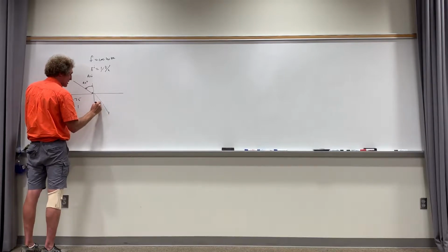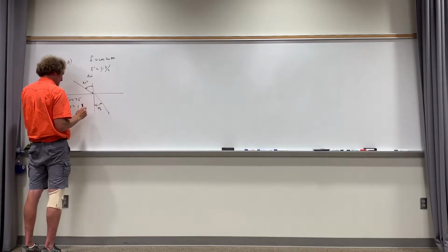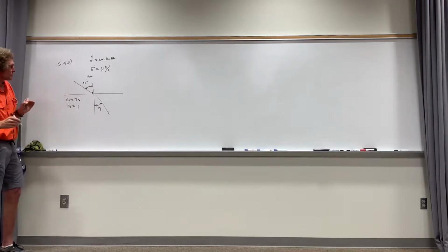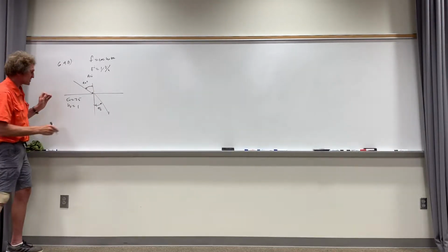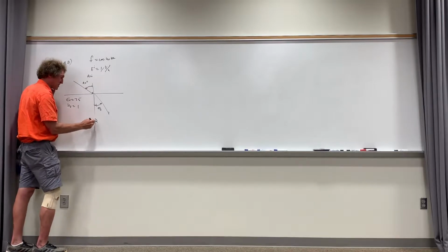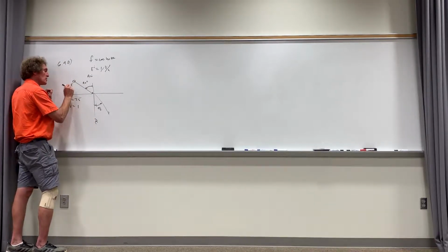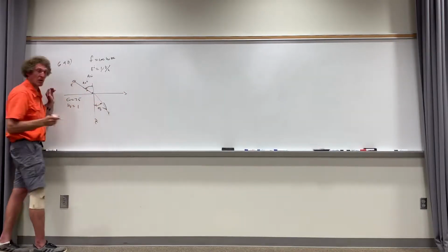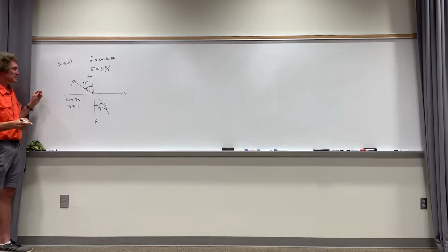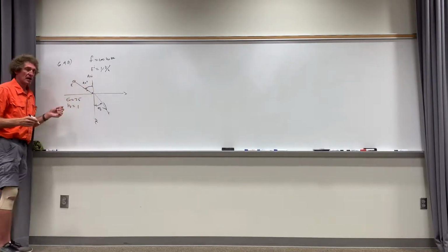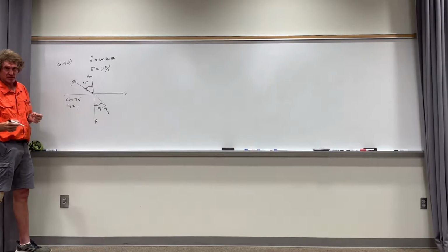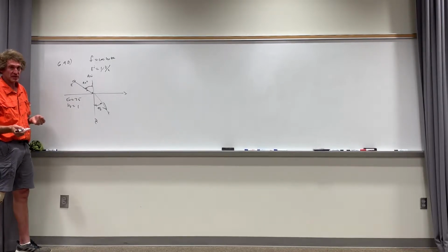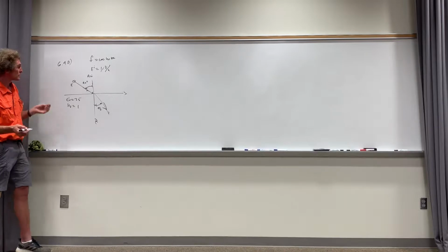And it asks to calculate the angle of transmission, the reflection and transmission coefficients. How is the field polarized? This would be TE. Yes, sir. All right, transverse electric means the E field here is out of the board, and this would be like the X direction. What I'm doing is I'm having this propagate this way, so it looks like it's hitting water. Are you with me, class? The angle of incidence is 40 degrees, and they want the reflection and transmission coefficients, or the amount of field transmitted and reflected. They want the angle of transmission and the reflection and transmission coefficients and the incident, reflected, and transmitted fields.